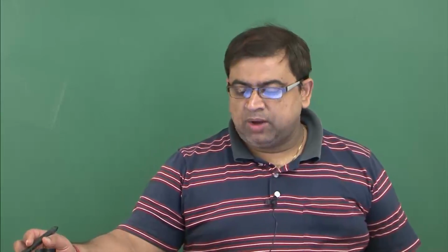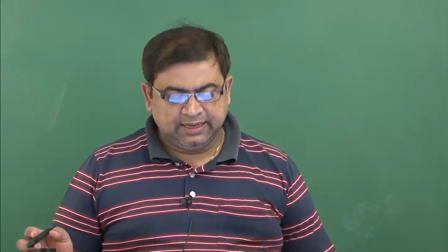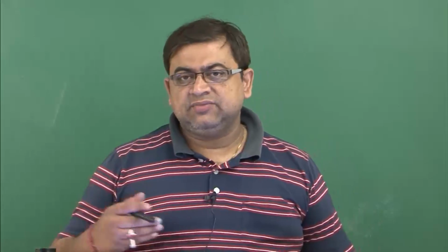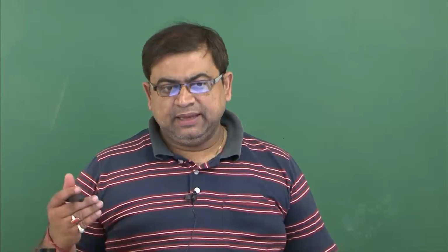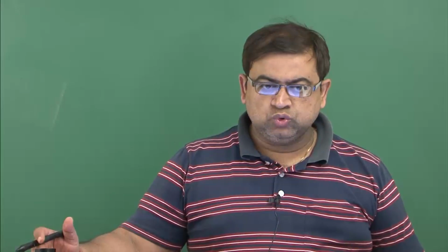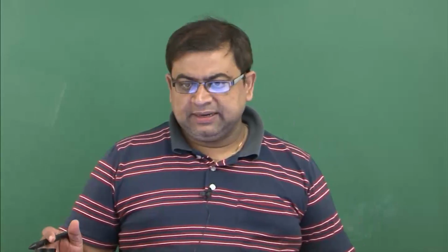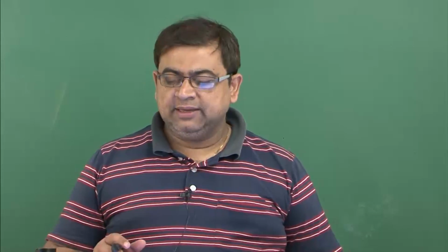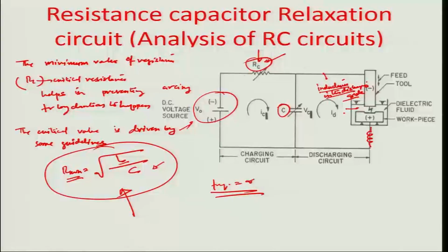So today we are going to stop at this level, but in the next class we are going to take up how this energy given at a certain rate is the amount of power that is going to do the material removal, and there are empirical relationships of power with respect to material removal through which we will try to predict some of the material removal rates. So if you change your circuit design, you could influence the material removal rate in terms of the power being delivered, and it depends a lot on the dielectric fluid and also on the electrodes, like the tool and the workpiece.